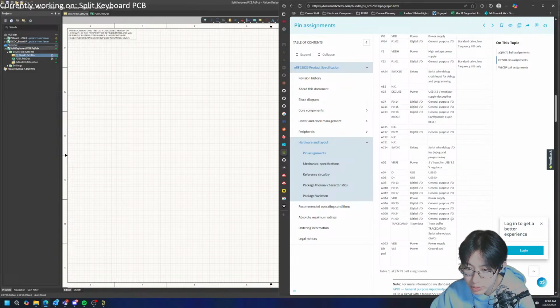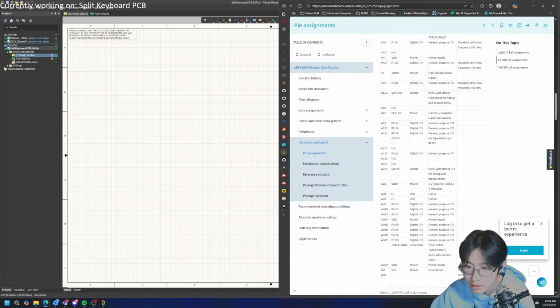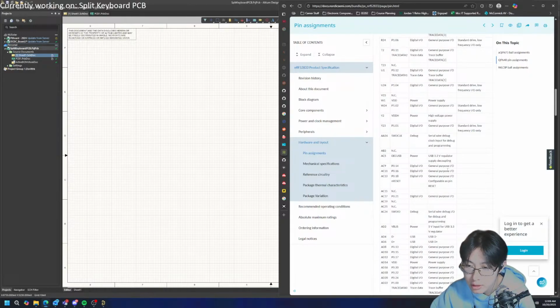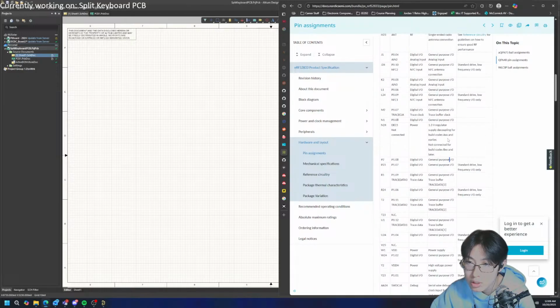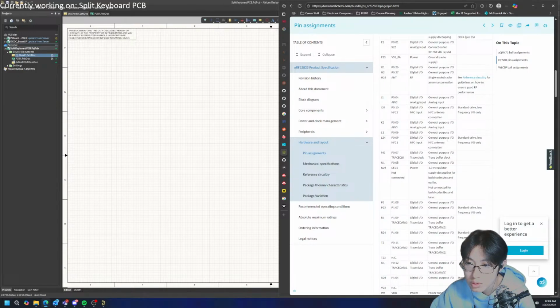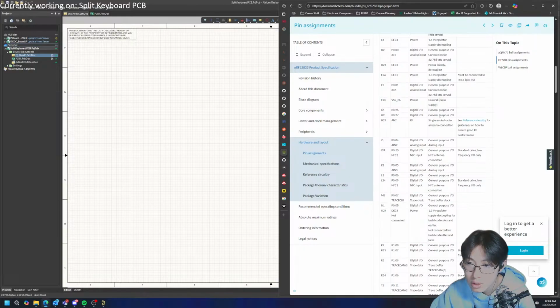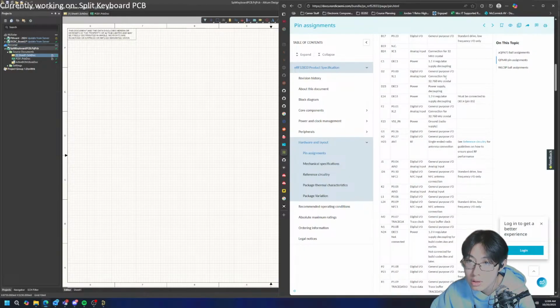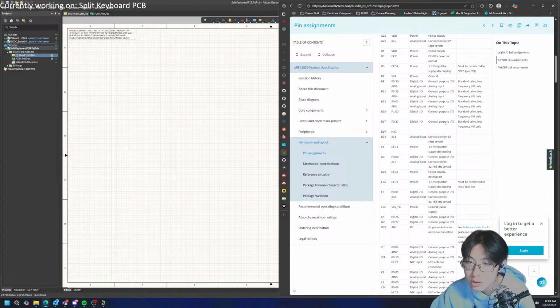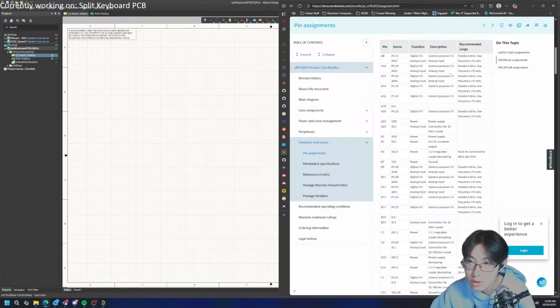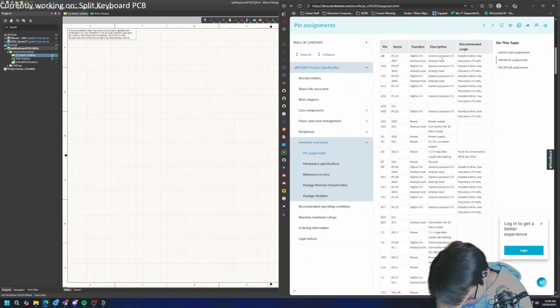Well, how many general purpose I/O are there? 1, 2, 3, 4, 5, 6, 7, 8, 9, 10, 11, 12, 13, 14, 15, 16, 17, 18, 19, 20, 21, 22, 23, 24, 25, 26, 27, 28, 29, 30, 31, 32, 33, 34, 35, 36, 37, 38, 39, 40, 41, 42. 42 would mean a 6x7 matrix, which is, yeah, more than enough for a split keyboard.